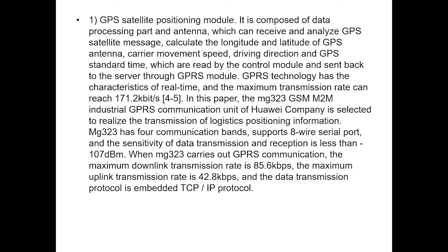MG323 has 4 communication bands, supports 8-wire serial port, and the sensitivity of data transmission and reception is less than -107 dBm.